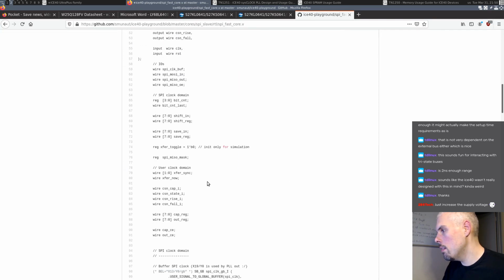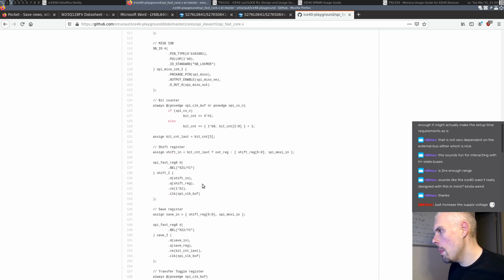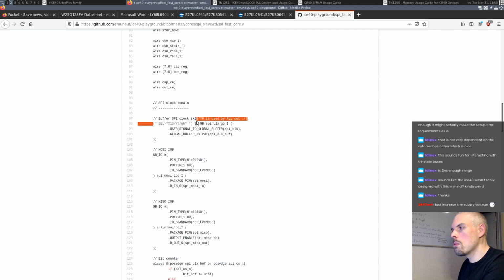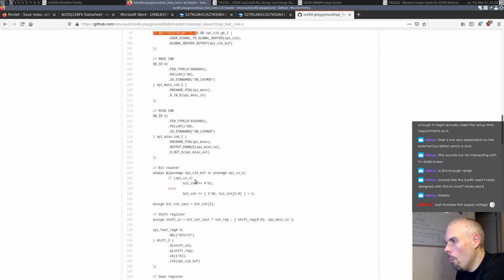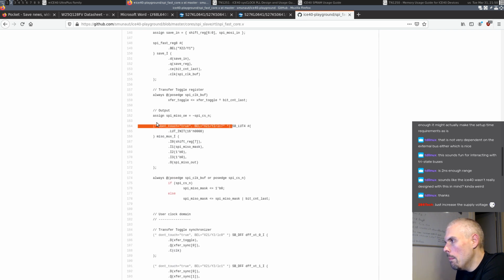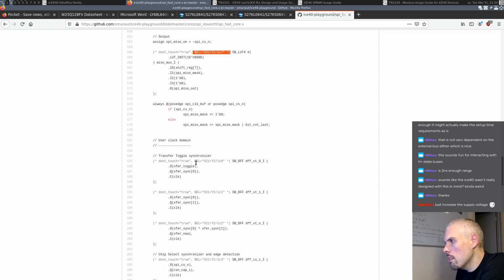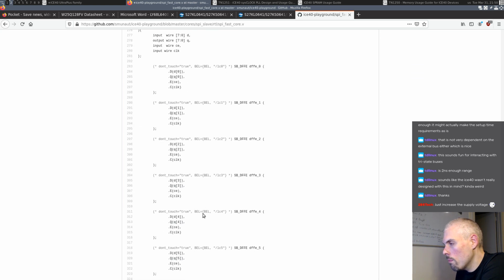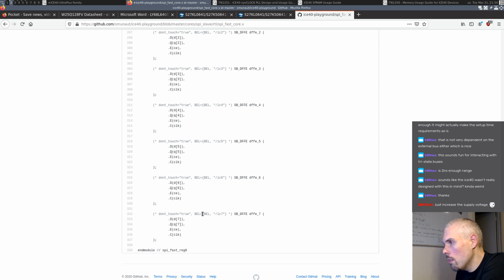And in that core, I had to manually, like if you look at the actual source code, there are things like that, where I basically hard-coded some of the resources at some specific site inside the FPGA to guarantee that I would meet timing. I have some LUTs that are locked into specific places in the FPGA for several things. And I had to do that for several reasons.